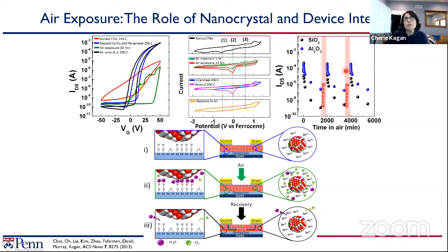And what we learned through analytical measurements is that as we anneal, the indium from the electrodes would go in and sort of getter and fill these defect states. If you anneal without indium, those defect states stay. And so it becomes actually much more stable over time. And so there are two key things: the influence of things like air, which has oxygen and moisture, also affects this interface trap density here between the two. And so annealing drives out the oxygen and the water. And then we can also sort of repair the nanocrystals.